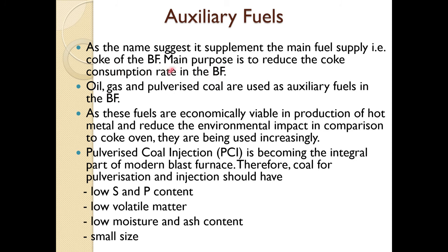We will actually do some more calculation on how much coke we can really substitute by other supplement fuel, because not 100% of coke can be substituted by this. Oil, gas and pulverized coal are used as auxiliary fuel in the blast furnace. Nowadays, even natural gas, biomass, and municipal waste, treating them and using them, is going on at a few places.